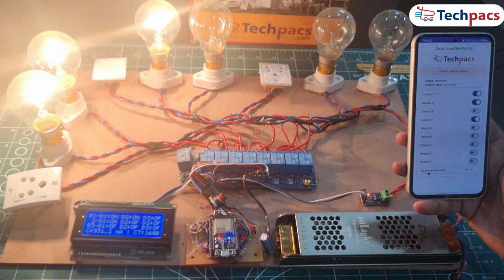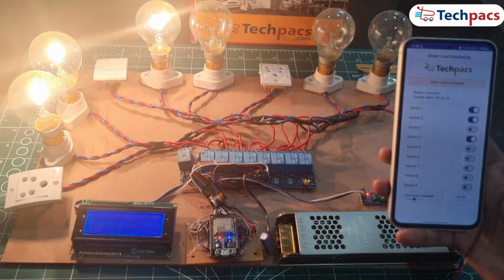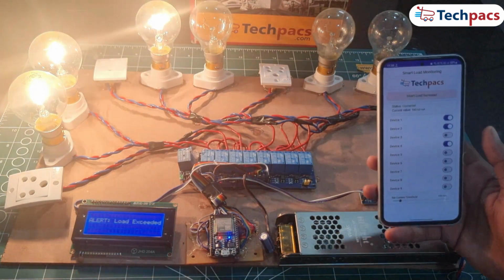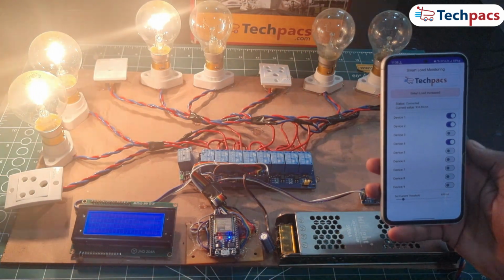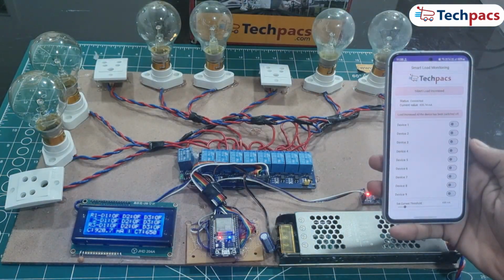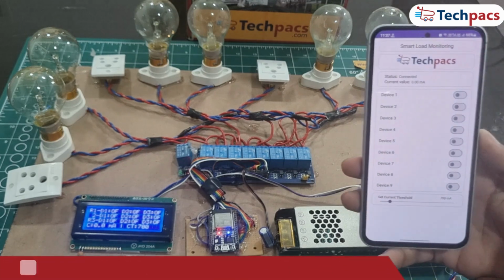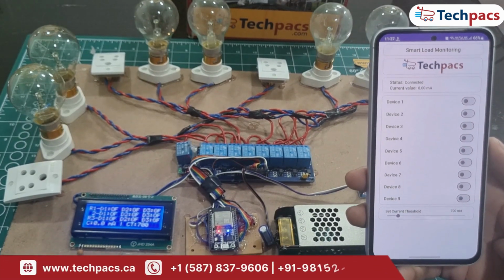As expected, once the current load exceeds the set threshold, it shows alert on both hardware and mobile app. If the load is not decreased within 10 seconds, all devices will be turned off automatically. Let's observe what happens when we decrease the current load by manually turning off a device during an alert.